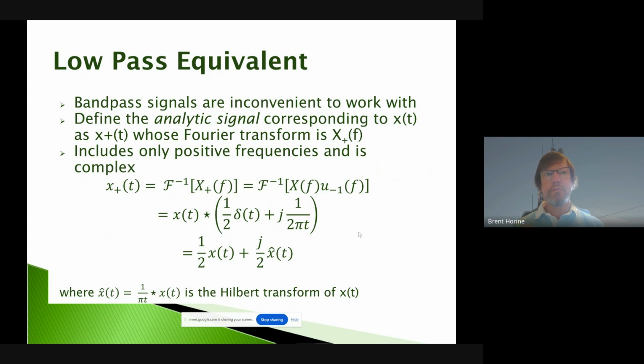we're going to need to oversample it, right? To satisfy the Shannon sampling theorem, and to make sure we're sampling above twice the highest frequency in the spectrum. So now we need to sample at about 4 giga samples per second and beyond, just to evaluate a megahertz, or maybe 10 megahertz, 20 megahertz type signal.